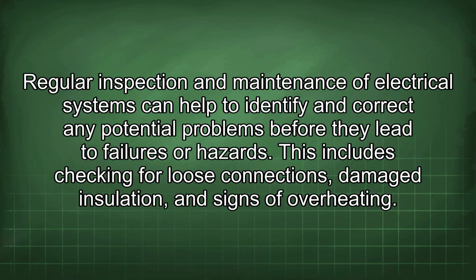Regular inspection and maintenance of electrical systems can help to identify and correct any potential problems before they lead to failures or hazards. This includes checking for loose connections, damaged insulation, and signs of overheating.